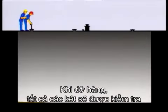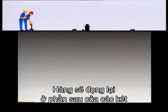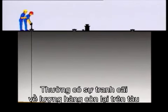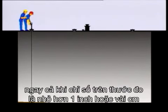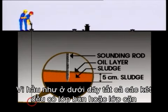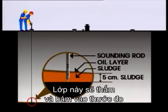When the cargo is discharged, all tanks will be searched for remaining cargo on board, ROB. The tanks will be dipped only in the aft part. The special sounding rod fitted to the MMC is used. Too often there is discussion of ROB even when the indication on the sounding rod is less than an inch or a few centimetres. Most likely there is unpumpable mud or sediment in the end of the tank. This layer may be penetrated and a thin layer of oil smears the rod.